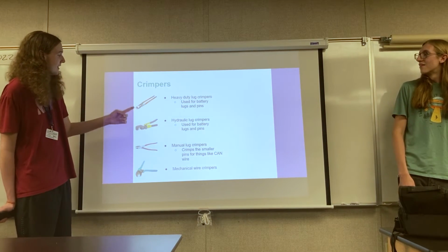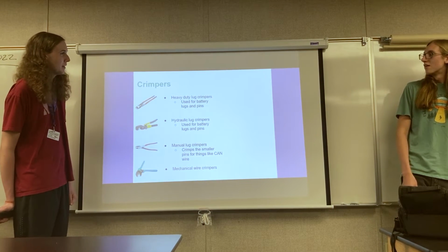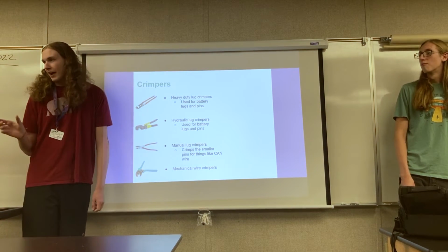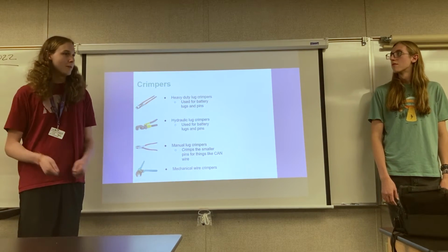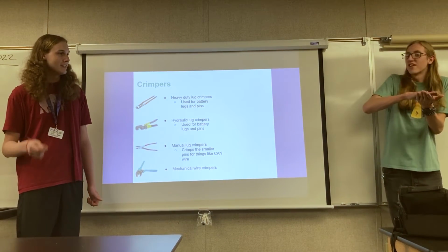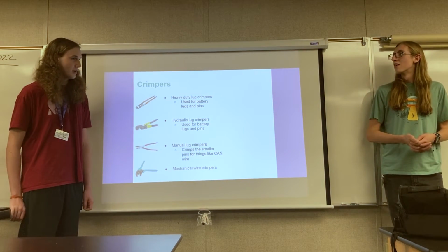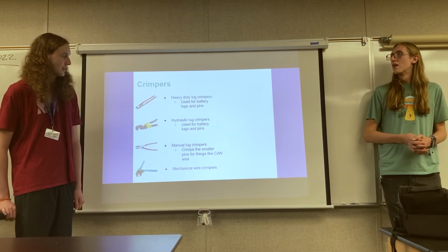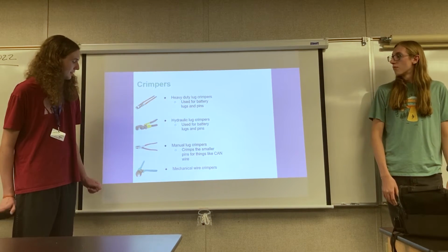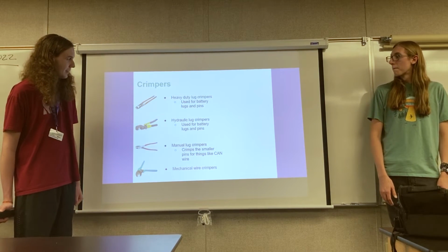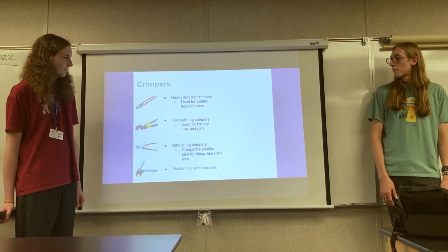Oh yeah, here are the big things. Crimpers are what we were talking about earlier. You have a plastic piece with metal in the center, and they use a lot of force to squeeze the wire between the two ends of it. So it's an alternative to soldering; it just uses force to hold the wire in place. They're dangerous if you put your finger in them, but they can also be useful for connecting things if you don't want to solder.